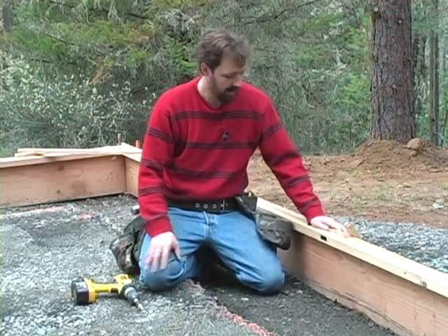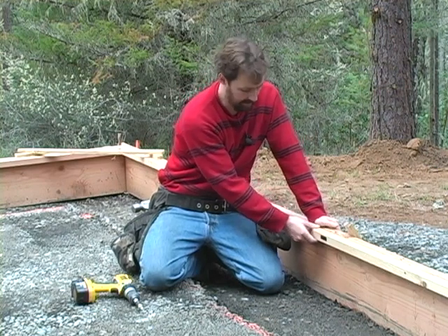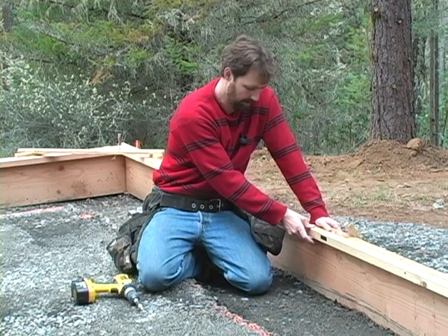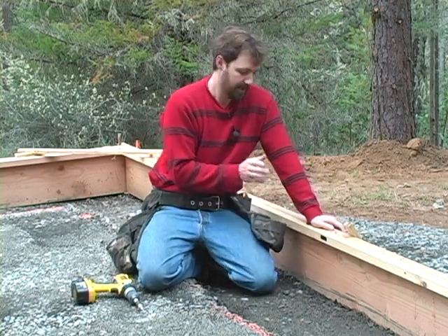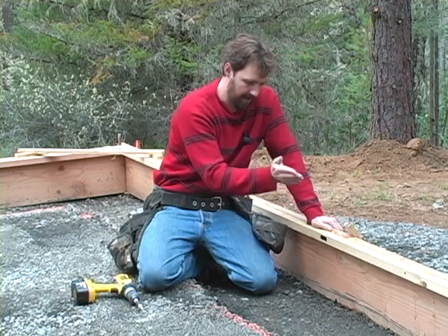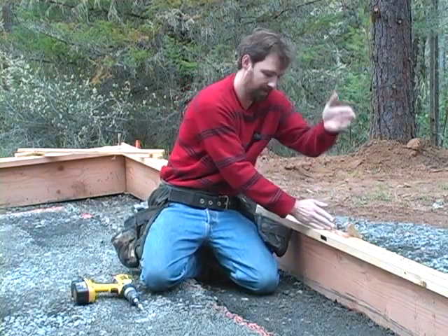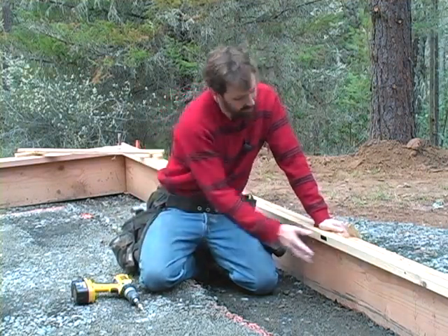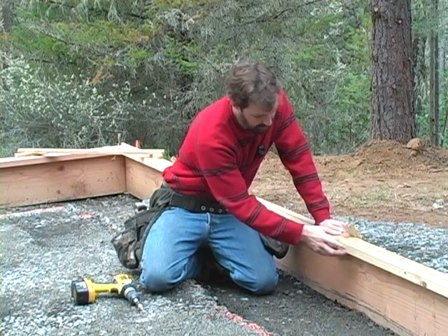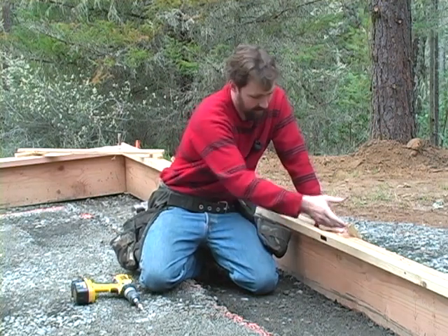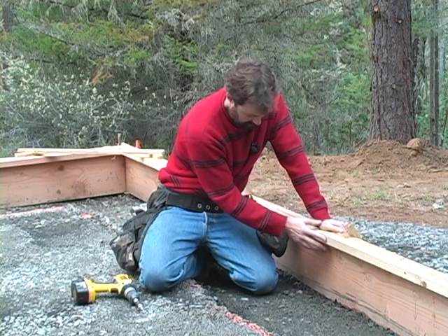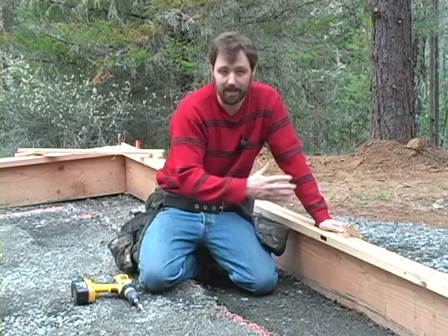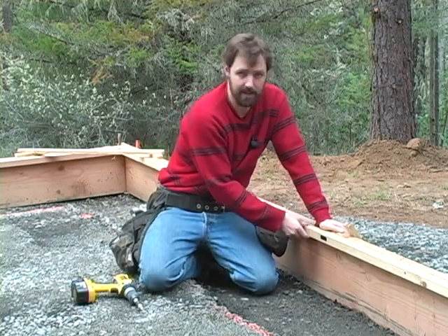With the form board straightened now, I've come in and put a plaster relief on the inside here. We're doing a straw bale wall here, and we have 1.5 inches of plaster on the outside of the wall. So what I want is a detail in the foundation where the concrete comes down, moves out, and goes down to the outside so that my plaster can then come right down and line up close to flush with the outside of the concrete. So here I've used a 2x2, screwed into place about every 2 feet at the top edge of the form. Then I put a little piece of electrical tape on here just to keep the concrete out of the threads of the screw so I can actually get this thing off when I want to take the form out, and I can reuse these again at a later date.